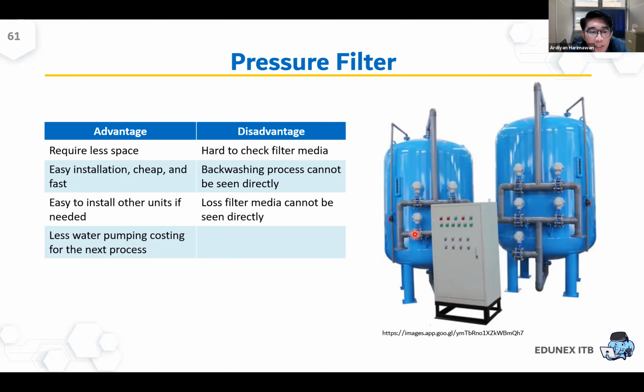Well, the operation is okay. It requires less space, and it's easy to install. And there is less water pumping, because it's helped by the pressure. However, the disadvantage is that it will be difficult to check what happened inside the box, because it's not designed to easily open and close. You can open it during maintenance. Yeah, this is the pressure filter.